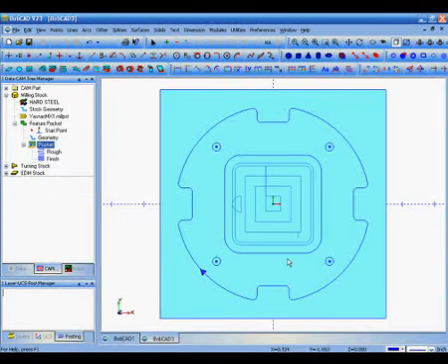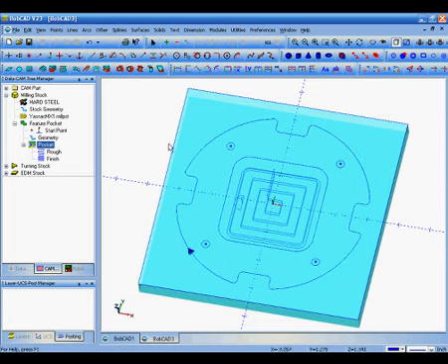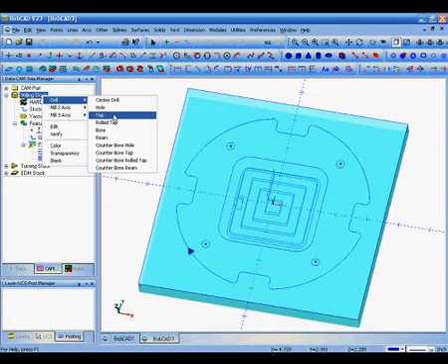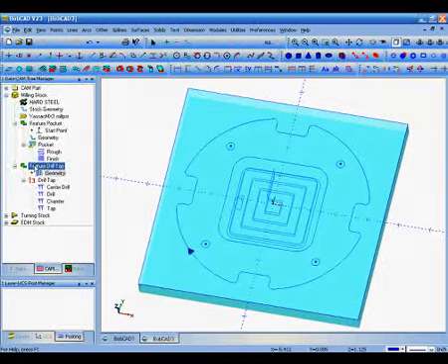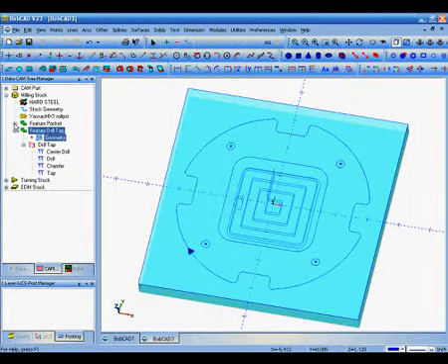Let's say that these are going to be 1/4 20 tapped holes. So what we'll do is we'll come up to our milling stock, right-click, and go to Drill, and in this case, Tap. Loads our feature Drill Tap. We'd also condense our pocket by clicking the minus symbol next to it. Just make it a little bit smaller on the screen, or collapse it.